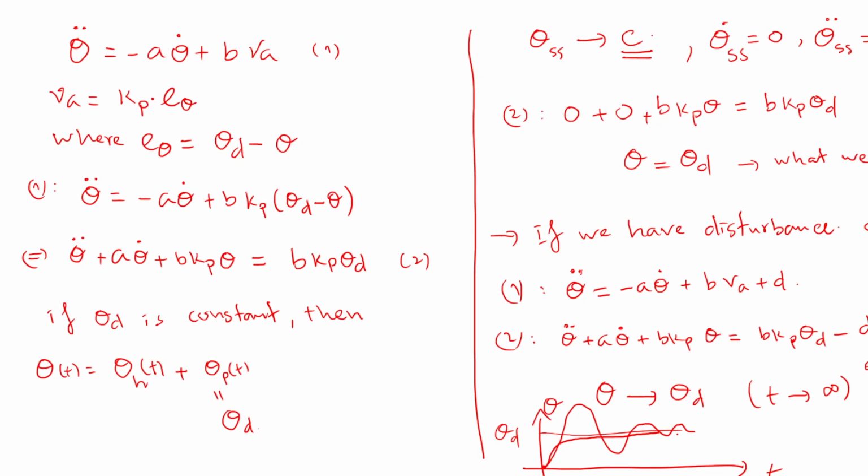I don't illustrate it now because you need to learn some more basics on Laplace transform and root locus. So I will explain later again using root locus. But just now, you should be aware that the proportional controller has limitations. First, it's not robust to disturbance. Second, the faster response you want, the more oscillatory it will be. Okay.